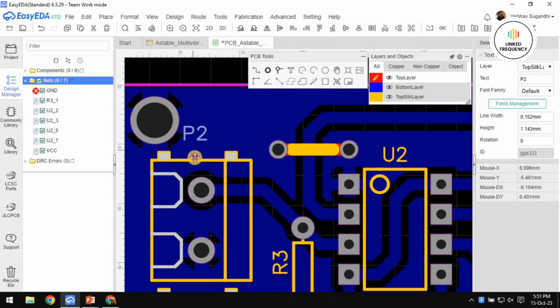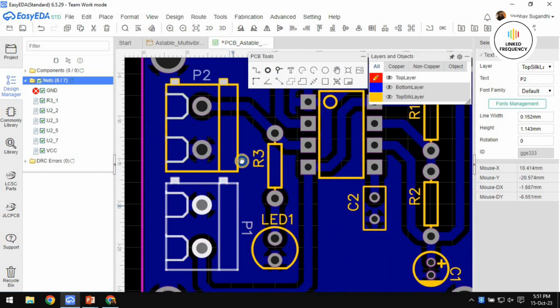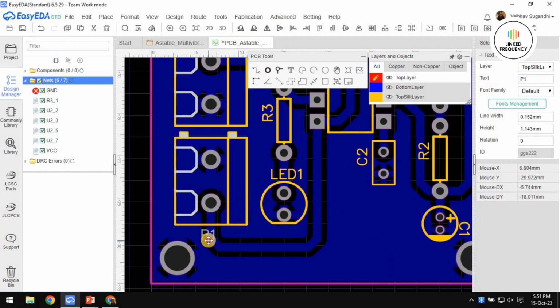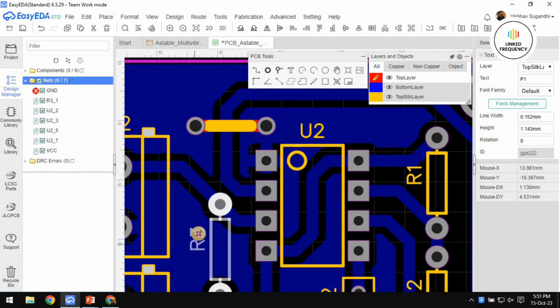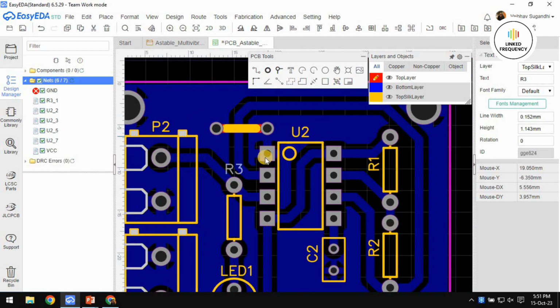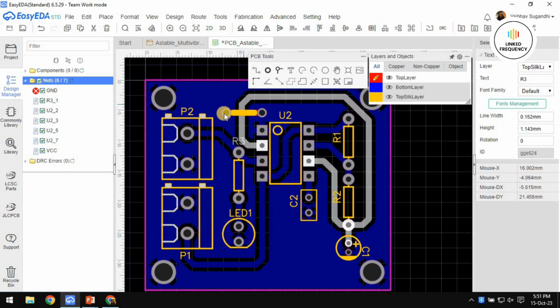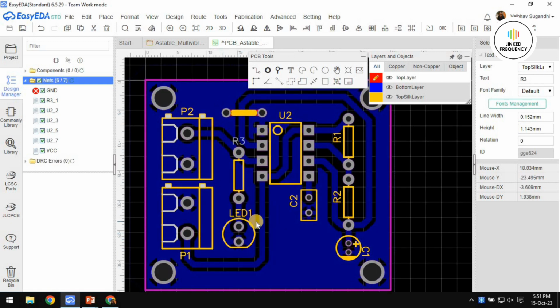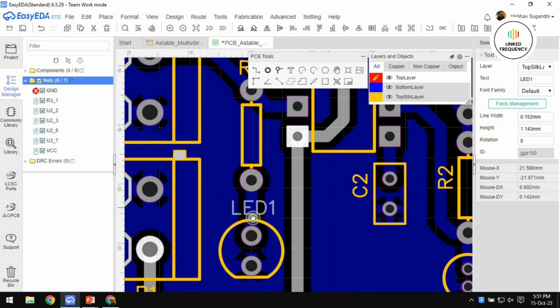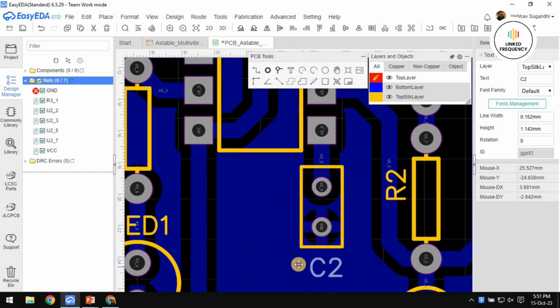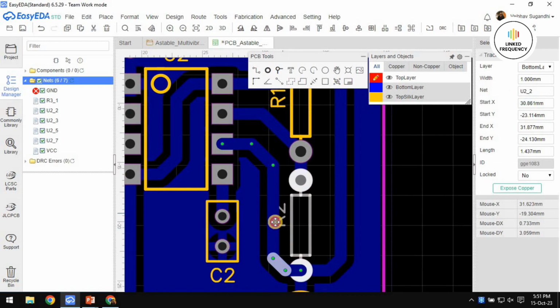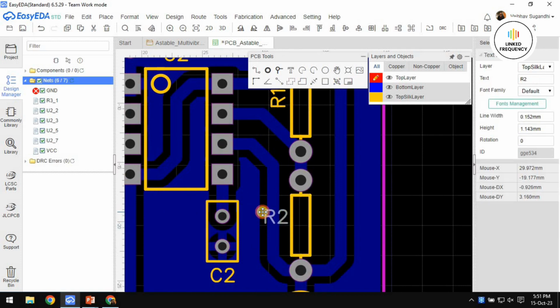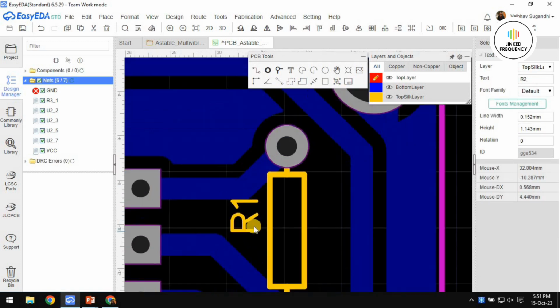Like this, we will get a lot of problems in higher-level circuits. And if the circuit design is very complicated, say, for example, you are having more than 2 to 3 jumpers like this, then it is not at all a good idea to go with the jumpers. It is better to use a 2-layer PCB design and complete your entire PCB in a much better way. So just make sure that you are using it in the right place, at the right time, with the right intention, and do not make it too complicated for the assembly process as well. So this is how the jumpers are used.